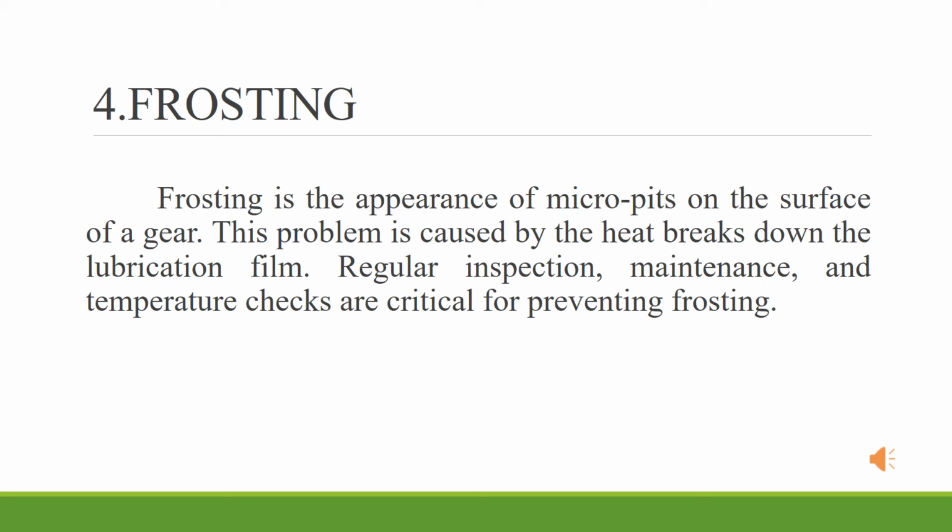Number 4, frosting. Frosting is the appearance of micro pits on the surface of a gear. This problem is caused by heat that breaks down the lubrication film. Regular inspection, maintenance, and temperature checks are critical for preventing frosting.